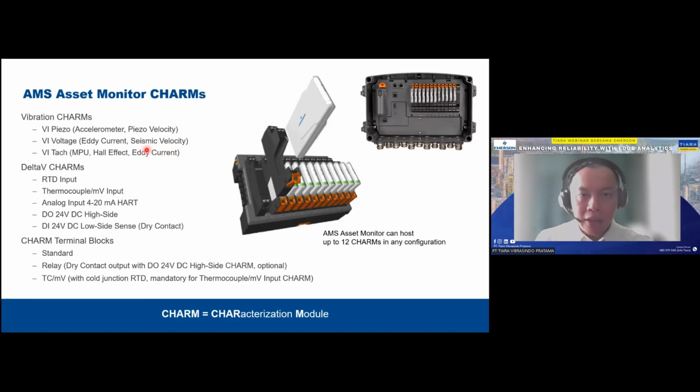Very easy. There's not many cards that you have to think about. Of course, the most important is the vibration cards, right? So currently we do have these 3 cards: piezo, voltage, or tachometer, right? So piezo, of course, is getting data from accelerometer or velocity sensors. Voltage, this is new. We just launched this maybe 1 year ago. This is to take in your eddy current sensors, right? So we can even take eddy current sensors for you to be able to do your sleeve bearing diagnostics and so on, right? And last of all, we also have tacho,